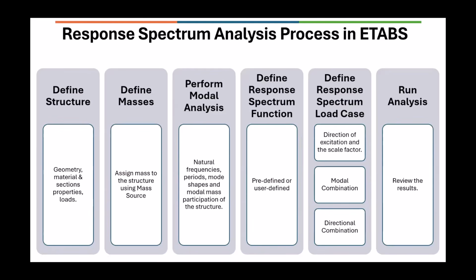To select and use, and then you will be defining a load case, which is the actual response spectrum case. In that, we will be specifying a few important things. One is the direction and the scale factor. We will discuss these in a while. And then you will be specifying the modal combination method and directional combination if you're combining more than one direction of loads.